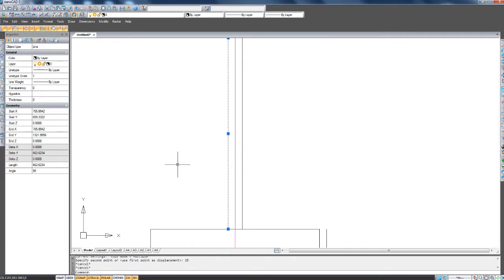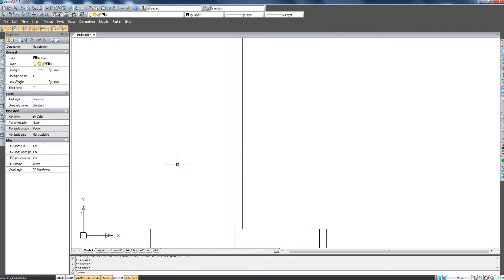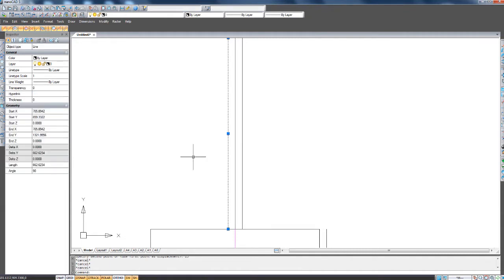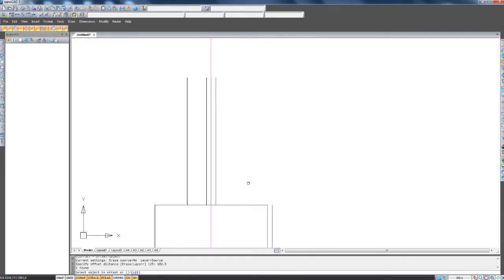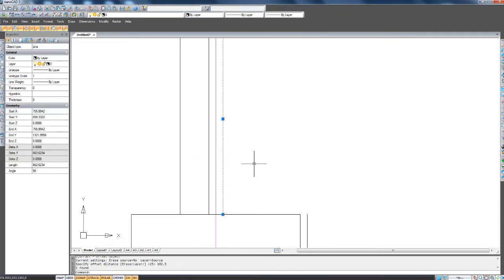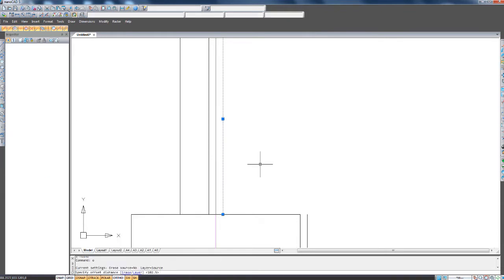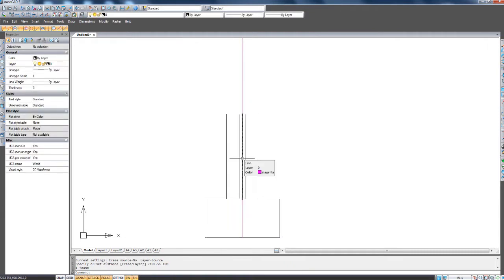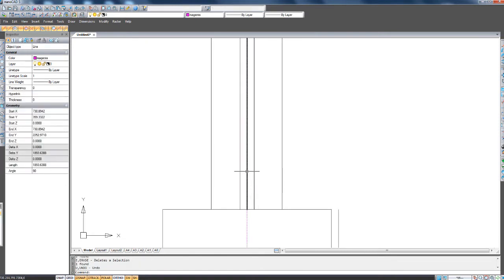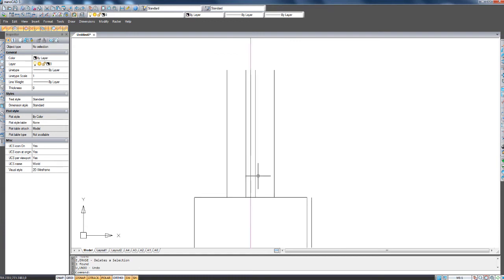So I'm going to try to offset it again. Click. Oh. 102.5 for the brick dimensions. Okay, that worked. And I'll try it with this. Offset 100 for the blocks. And that's worked. Why it was causing a problem before, I don't know. I'm going to leave this line in, this black line, because I'm going to do something with it later.